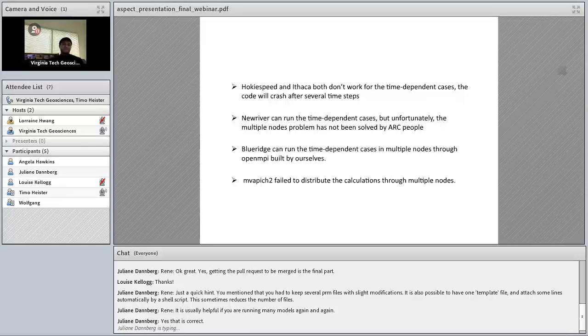If you encounter something like this, you need to look at what the error messages are and then work with somebody, an administrator or somebody from the community who might also be able to help. You go easier and easier, right? You simplify the problem trying to figure out what the issue is. The first thing would be to run a simple 2D problem on more than one node. If that doesn't work, you go to deal.II and run a deal.II tutorial program in parallel. If that doesn't work, you run an MPI Hello World program. And with that, you should be able to go to an administrator and say, look, this is broken.